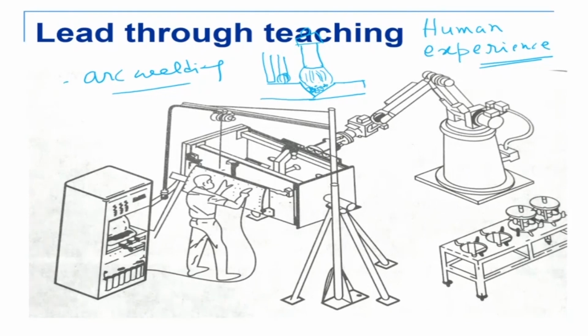If I take the top view of this and draw it here, this is my V weld from the top view. So he is depositing the weld and he's also moving like this, plus he's moving the electrode down. So there are two motions here. One is this bead formation or weaving, plus the electrode has to come down.